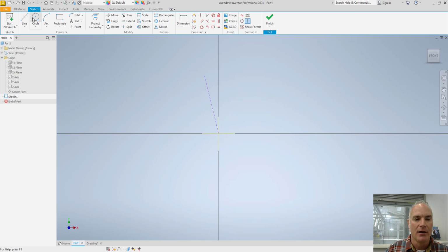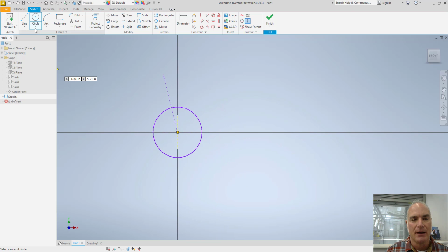So now I'll turn off my construction geometry by simply clicking on that button again, and I can start my part. On the left side, we have that arc that has a radius of about 13/16. That corresponds with a circle with a diameter of about 1 5/8. So I'll make my circle approximately the right size and shape, and then I'm going to put my line in.